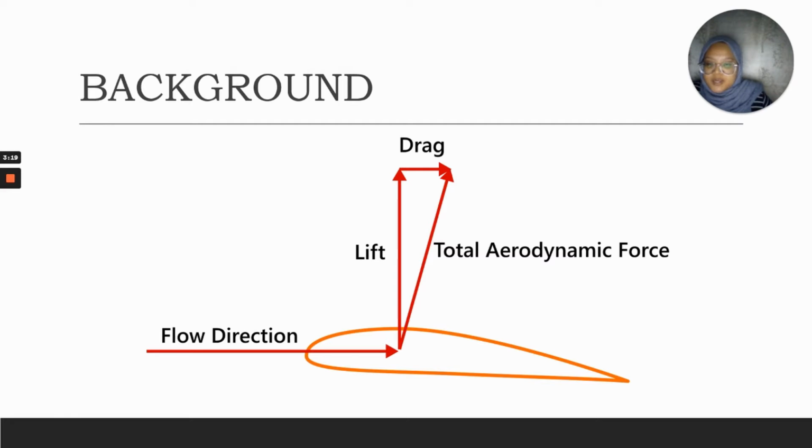The drag force remains constant whether the object moves through the fluid or the fluid flows past the object, as the relative motion remains the same. If the object flowing through the fluid is at an angle, the drag force won't be the only force that exists. There will be horizontal and vertical forces. The horizontal force is the drag force and the vertical force is the lift force. The lift force is perpendicular to the direction of flow.